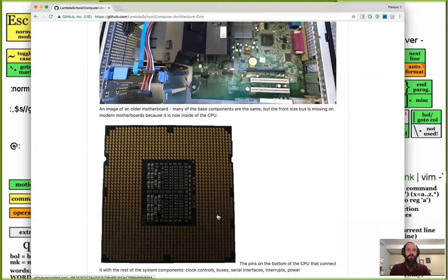And the rest of them are for things like a message that's called an interrupt, that any hardware device can send an interrupt back to the CPU. The CPU, it's very architecture dependent. You'd have to read the white paper on the exact CPU that you want to use to find out how many interrupt wires it has going into it. Maybe 32 of these wires are for interrupts, which means that 32 different devices on the system can register to have first-hand access to the CPU when they need to send a message.